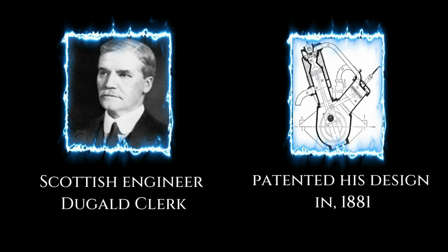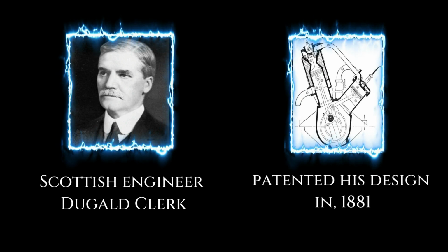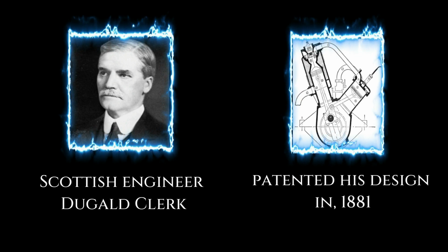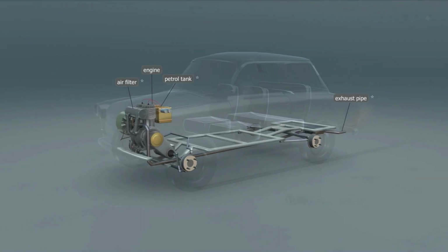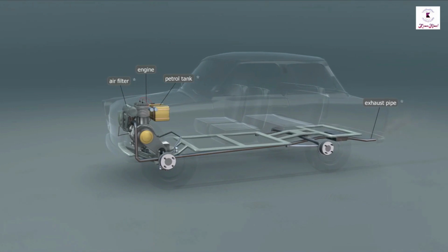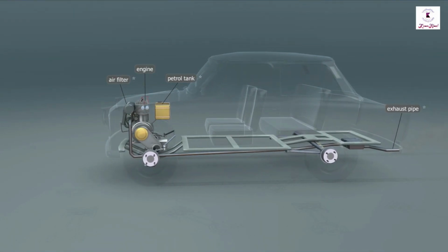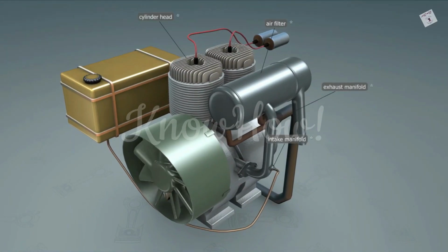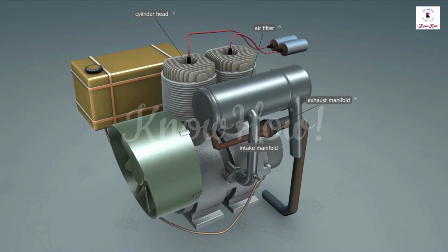The first commercial two-stroke engine involving cylinder compression is attributed to Scottish engineer Dougald Clerk, who patented his design in 1881. As the name implies, the system only requires two piston movements in order to generate power. The main differentiating factor that allows the two-stroke engine to function with only two piston movements is that the exhaust and intake of the gas occurs simultaneously.